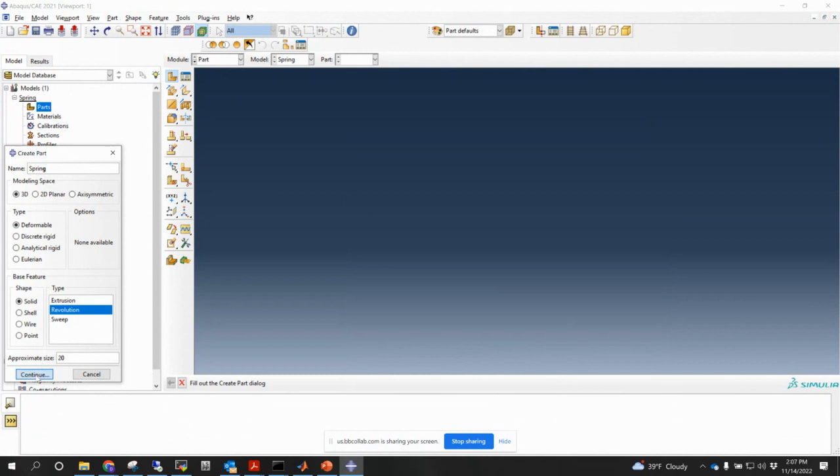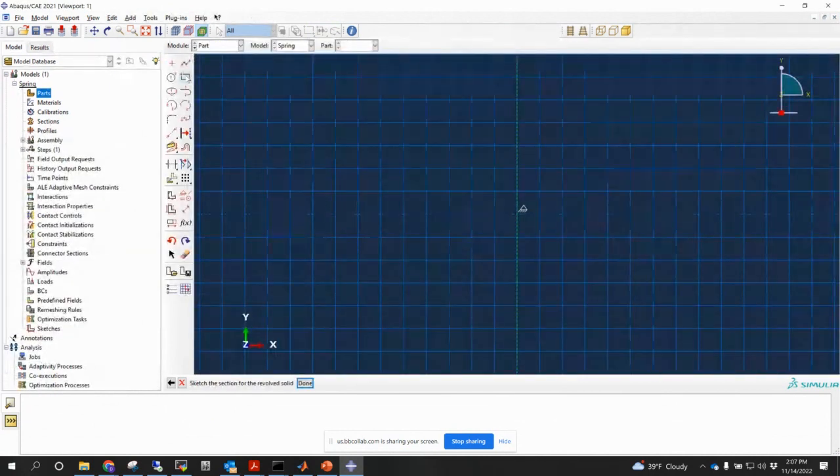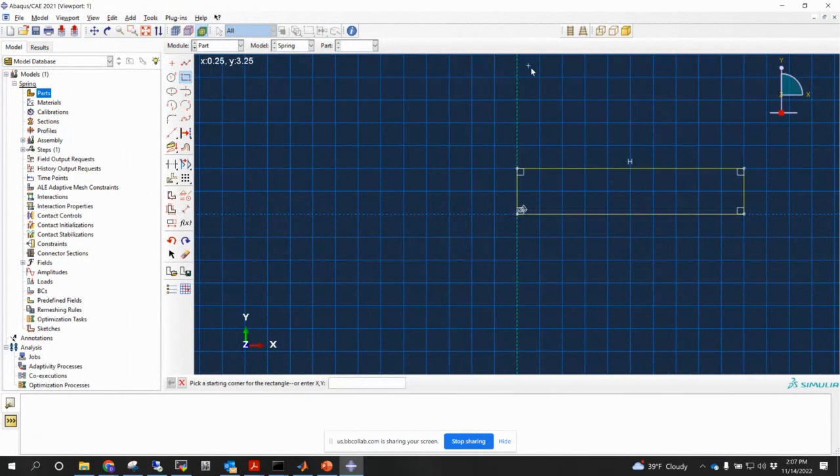And the size is 20. So the first thing that I'm going to do is to create a rectangle here, and it's gonna be 5 in X and 1 in Y. So it's just that plate that is gonna be on top. That plate, and it's something super important that I just taught previous week, these plates, we are gonna make them rigid. We don't want those plates to deform. We only want the deformation on the spring, right?